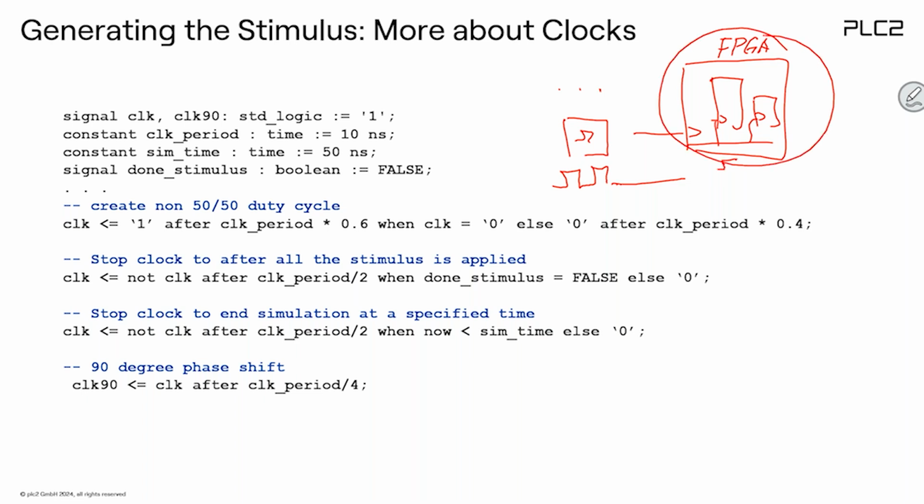So the complete simulation will stop fully automatically. Instead of saying run for 20 or 30 microseconds, maybe you don't know how long, you can say simply run. It will stop automatically when you stop the clock. So that's the idea of why it's a good idea to stop the clock.